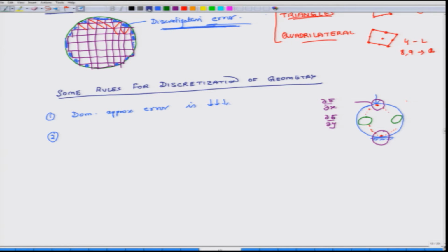So, if I am doing my discretization, we have to make sure that element size is small, and how small, you have to do several iterations on FEA and see whether you are getting the result in areas of high gradients. Because if you take a large element, then you will not be able to capture the sharp variation of the gradient. So, you have to take small elements, which means that when you are meshing this,